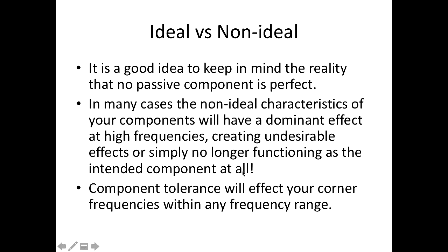So in your case, it is 20 megahertz. It is a low frequency actually. Megahertz is a low frequency, especially 20. Tens of megahertz is low frequency. It will work on a breadboard, in a good breadboard. So as a high-speed design engineer, I will not accept anything as high frequency below 1 gigahertz.